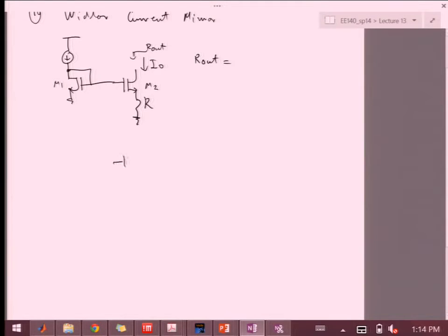If we had a simple output, then this would be Rout equals ro. So here we have this constant thing where if there is a resistor of some form in the source and you're looking from the drain, you get something. Okay, so I'm hearing ro. What else? Parallel with R. Okay, any other suggestions?